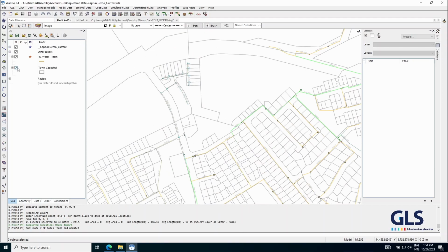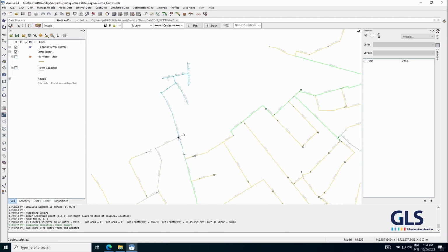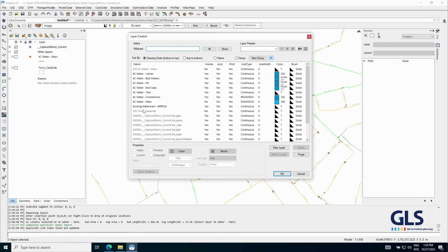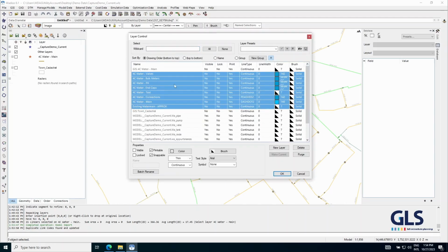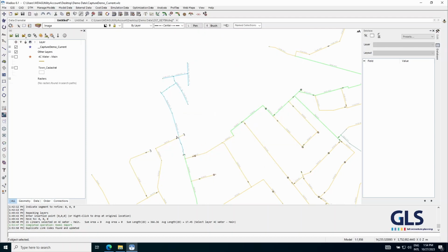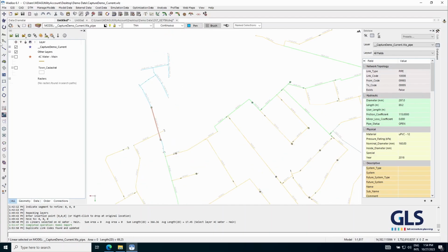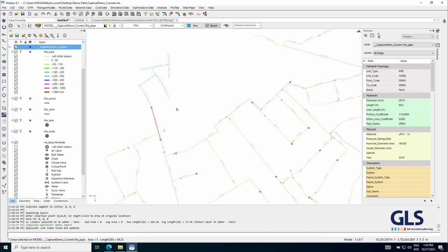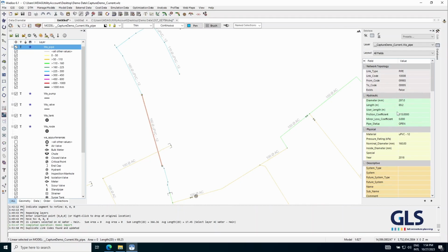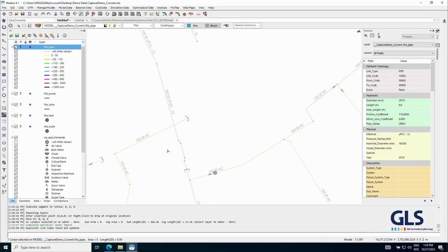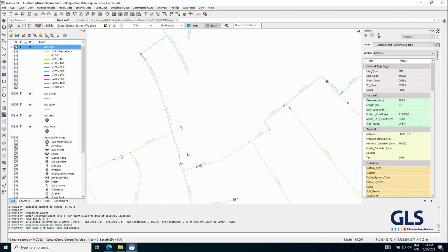Okay, so just turning off the cadastral and the GIS I created, and let's turn off all our new CAD layers that we've added. Okay, just increase that. Right, so here we can see that the nominal diameter has been filled, but some default value has been added, which is the last pipe entry. So we're happy with that, except that we actually want the correct values.